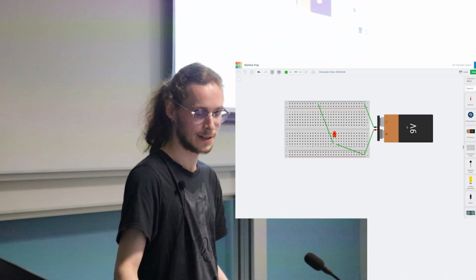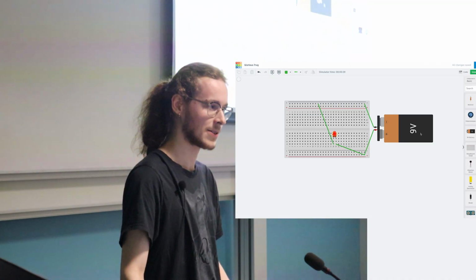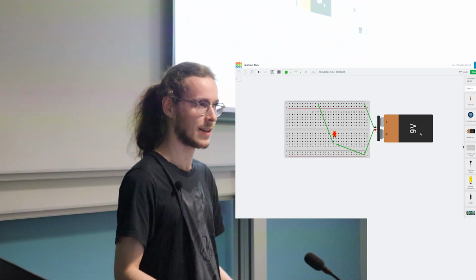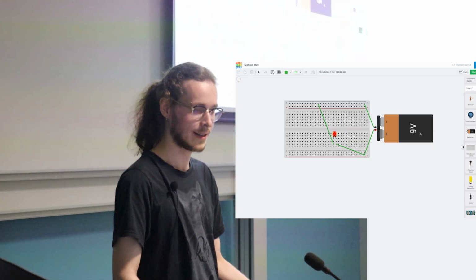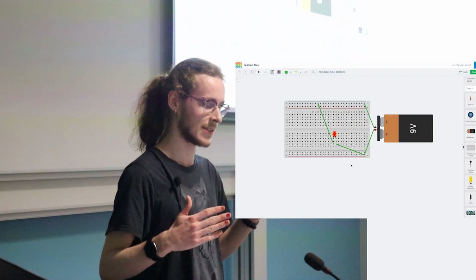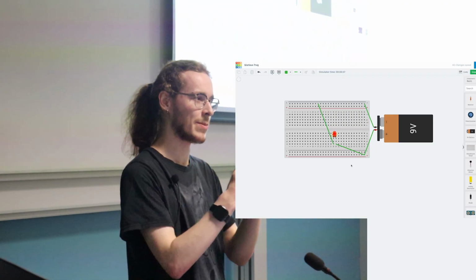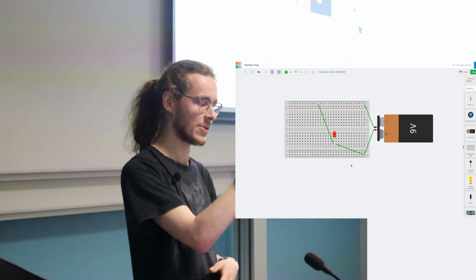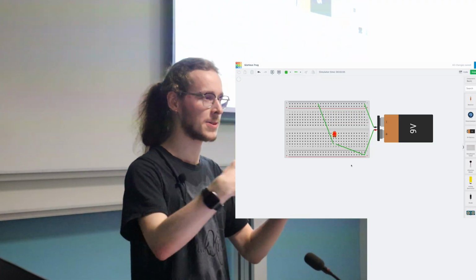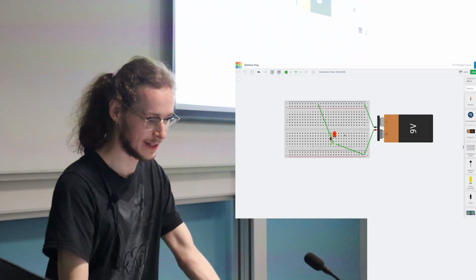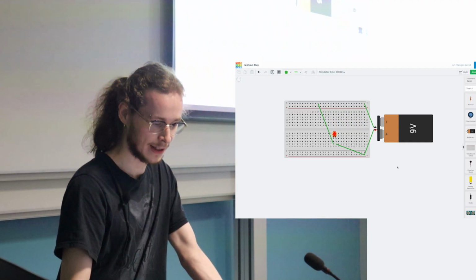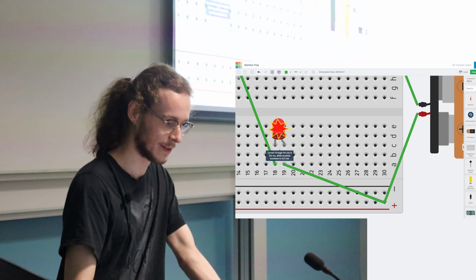So we can't really, well, say we need to use 9 volts. Maybe we need 9 volts in other places, but in this specific part of the circuit, the current is too high. So what we can change is the resistance. So you can imagine this as adding like a narrower pipe. Like say you cut your main pipe in half, and then you put a smaller pipe that connects them. It's like a bottleneck which prevents too much current from flowing through this circuit, and then the current will be at a safe enough level for the LED.